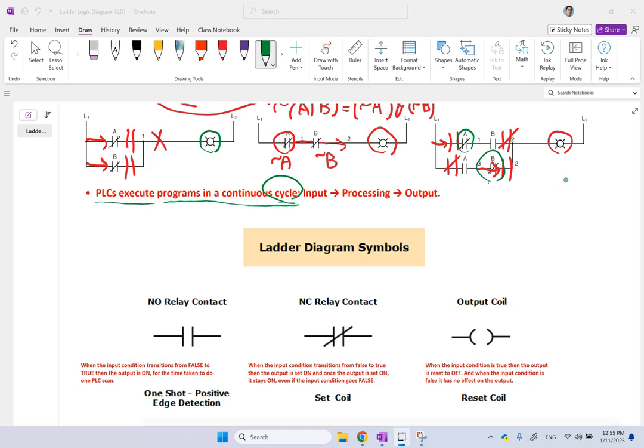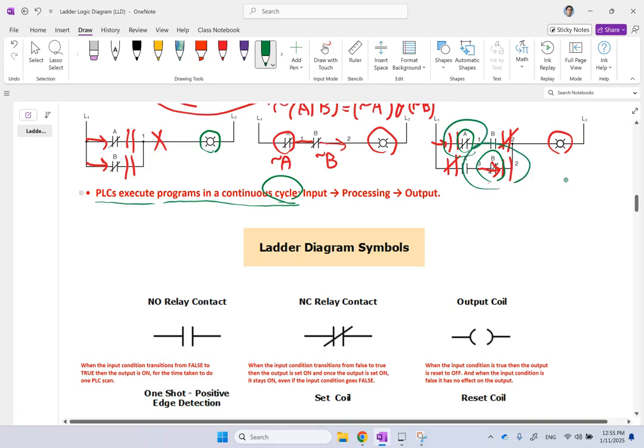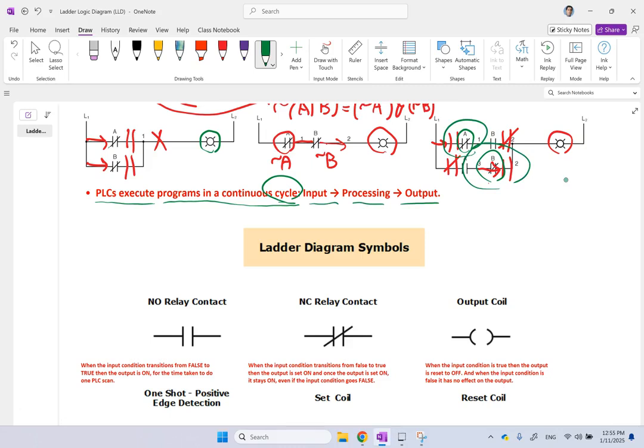Or if they are very slow changing, but the processing cycle of the PLC is fast, then before any of them changes, PLC can go through several cycles. Okay, so the speed of the PLC processing the code and the ladder logic is not the same as the speed of the sensors or actuators going on to off or off to on or anything. So we have to pay attention to that.